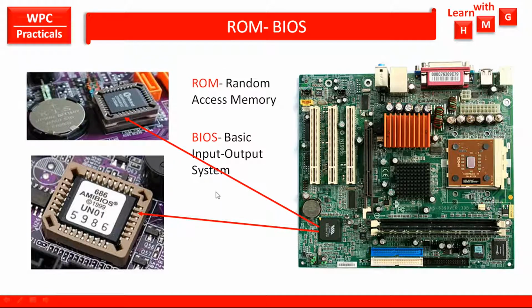This is another type of memory, which is the permanent memory, where your basic input output system is recorded or programmed, and when you start your computer, initially this particular program, that is the BIOS program, runs, and it checks all the circuits or devices connected to this motherboard, whether they are working, whether they are getting supply, and all these things checkup is done by this program. It is available permanently on this particular chip known as the ROM BIOS chip, and whenever the supply goes off, the supply is provided through this particular battery, which is beside this ROM BIOS, this is the CMOS battery.